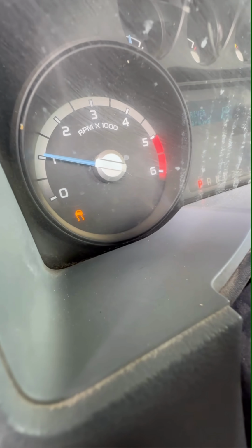If your ABS light is on, come over here. If you have wheel speed sensors like this one, check to make sure that there's not too much of a gap in between the tone ring and the speed sensor. That one's okay. Now what about this other side? Notice how this one has a large gap. This will cause your ABS light to come on. What we need to do is adjust it with a screwdriver. Push it all the way in, just like that.